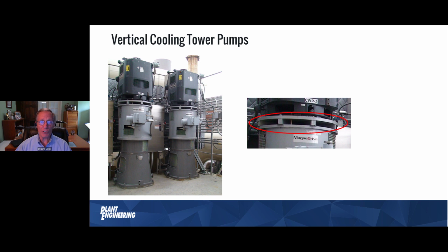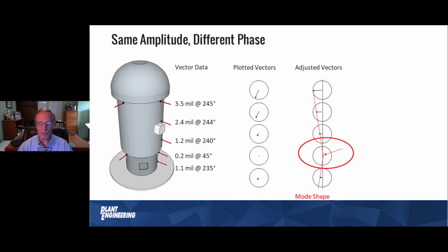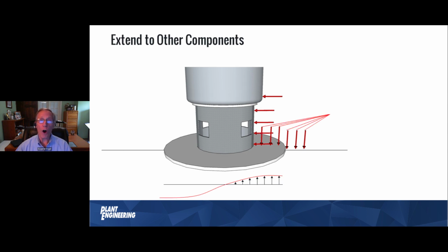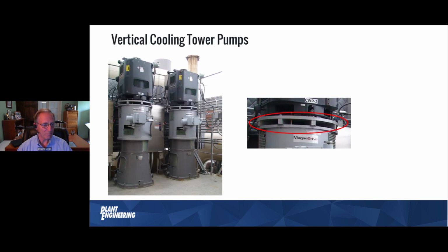So if they change the speed of this machine when they get to one particular frequency where that plate wants to vibrate, its natural frequency, all of a sudden the vibration goes way up. So this is a very real problem that's illustrated here. And you see the difference between that and looseness and base plate resonance. All would be indicated by the operating deflection shape.